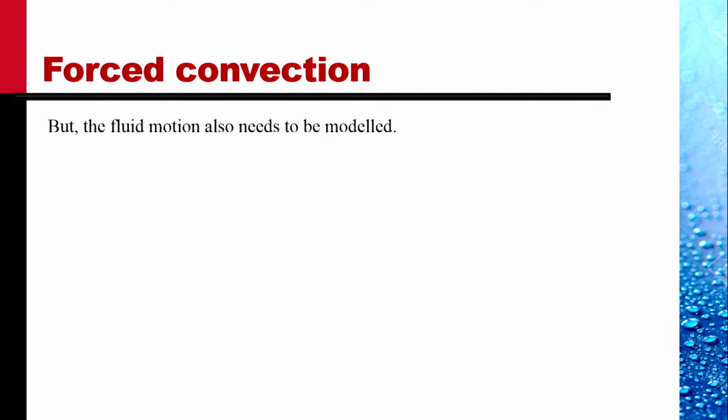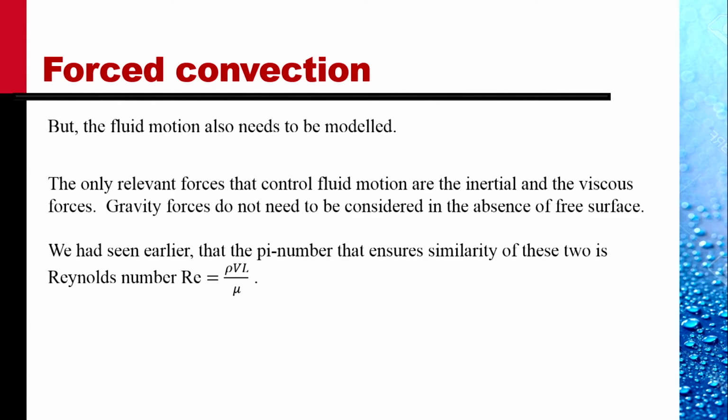In addition, we need to model the fluid motion. The only relevant forces that control fluid motion are the inertial and viscous forces. Gravity forces do not need to be considered in the absence of free surface. The pressure forces also need not be considered because the cavitation is not involved, so Euler number is not important.